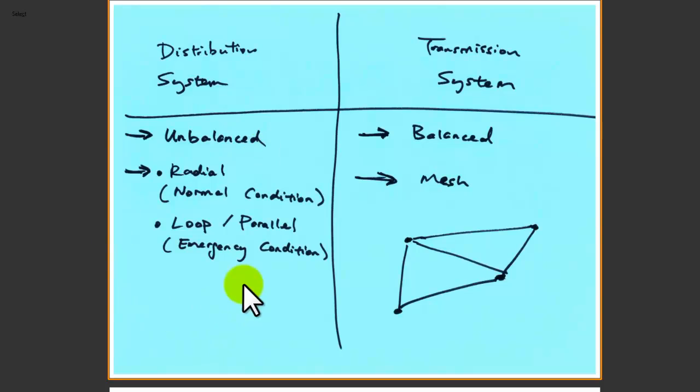Of course, we will also go through the graph traversal, backward and forward, along a distribution feeder, which in graph theory we refer to as a spanning tree. So you have a root node and then child nodes in the network. The root node is referred to as the feeder head, and the child nodes are actually the loads of the feeder. That's the difference between these two networks.